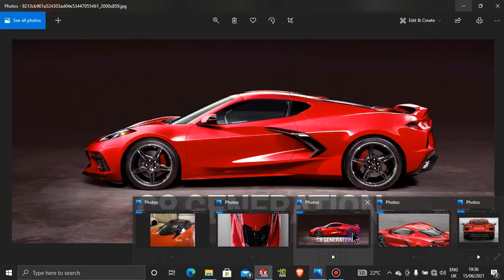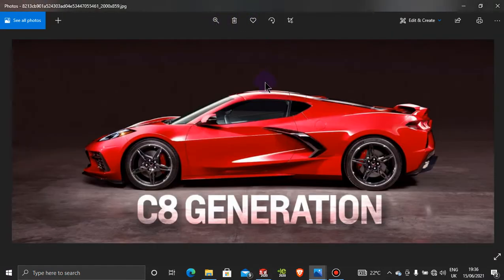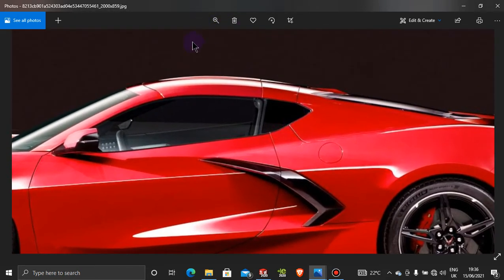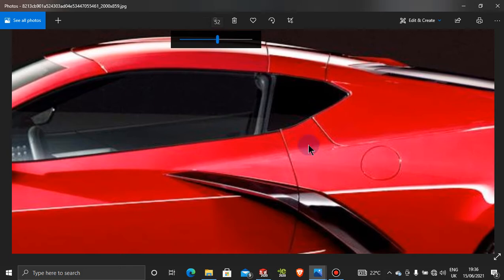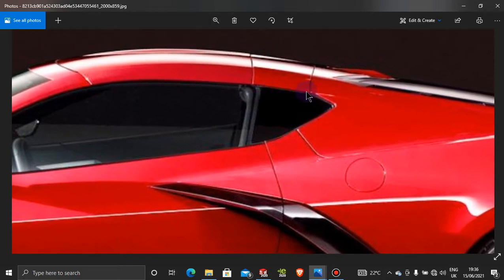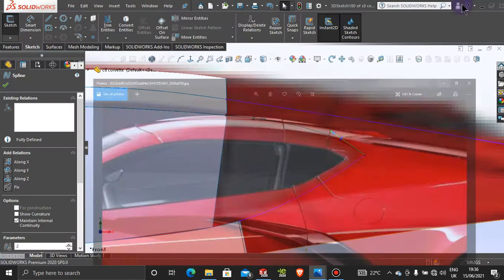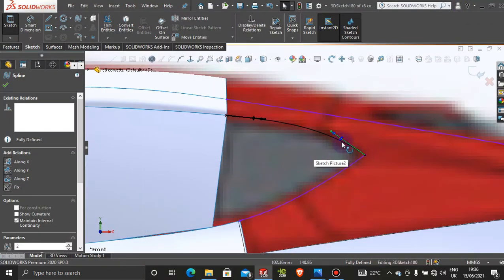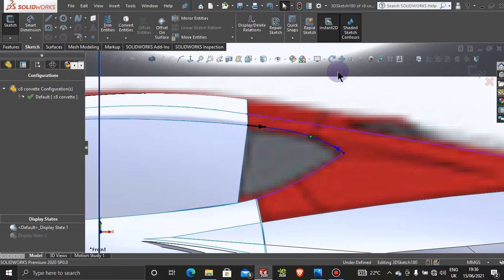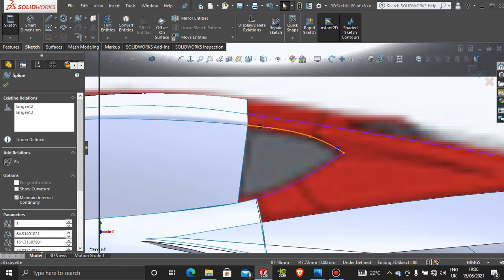All right. So it has a little bit of sharpness in that corner there. That it goes up. It has a little bit straight here and then sharp here. So let's try to tackle that. So this is where the corner is. So let's grab a spline point, drop it here, and click back on that line and add our control polygons.